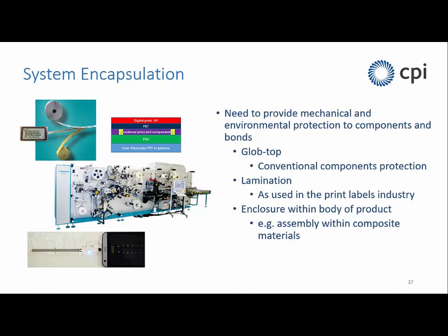In this case, the inlay circuit, this is the printed stress sensor going out to the left-hand side, strain gauge, the circuitry in the center. All of that is printed onto a 50 micron substrate. We then laser away any of the material that's not needed so that it's not interfering too much with the composite assembly. But then this can then go into a standard composite assembly process with the appropriate layup and different types of materials. It can withstand reasonable pressures and temperatures to form a perfectly standard piece of composite.